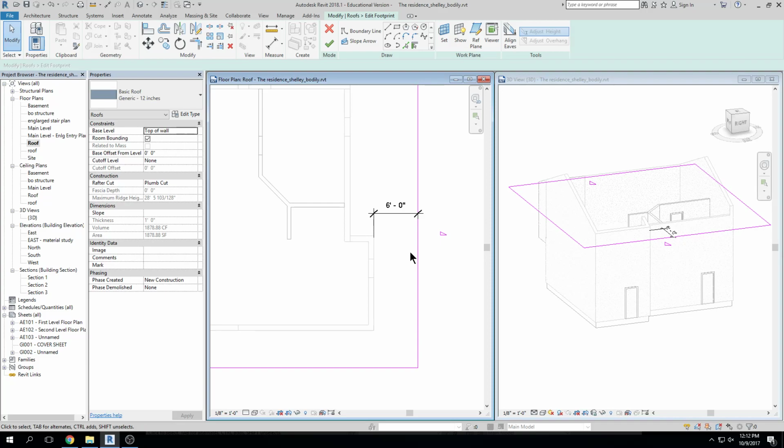My roof is not quite closed when I go to floor plan. There is like a hole. It's probably a view range. It's probably cut. It's your view range. Oh, okay. So if you go to your view range, you'll have to define it. And it may take some playing around. I associate view range with LT scale in AutoCAD. It doesn't really affect your view very much, but do whatever you need to do to get it working. It's a pain in the neck. Add that little gem.